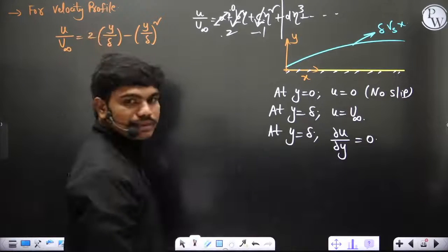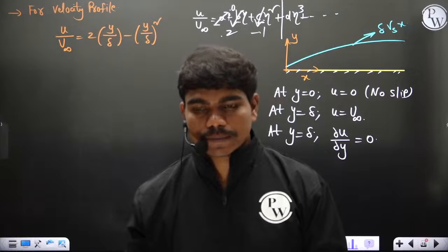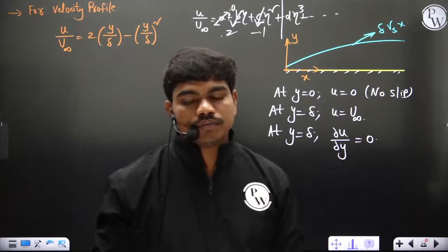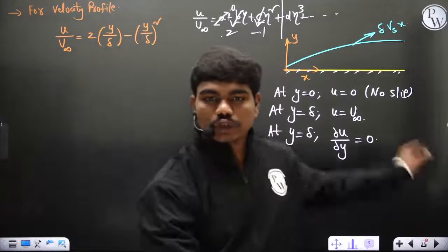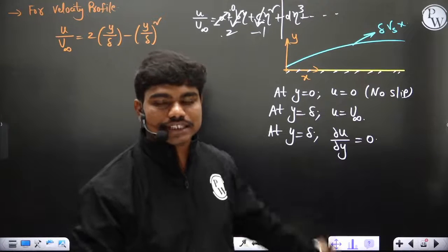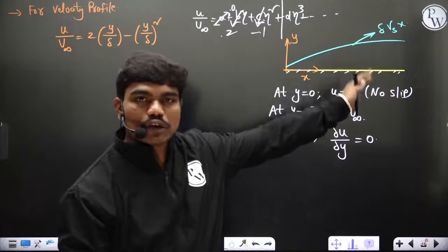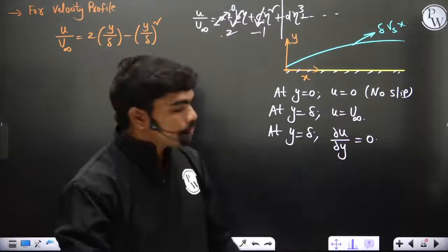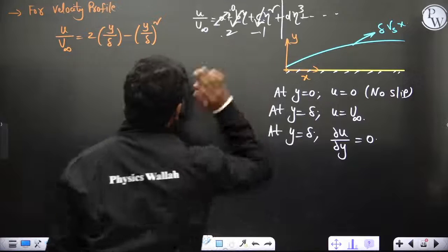That's why this profile is important, and you see it many times in all the fluid mechanics books. Clear? The reason you see it so frequently is this. If you want higher accuracy, you can define more boundary conditions, like the second derivatives being zero, and extend this up to 4 or 5 terms. But then the calculation of delta, theta and all these quantities becomes very elaborate. That's it. Anyway, this is the quadratic profile. I'll leave that. Somewhere you can see it.